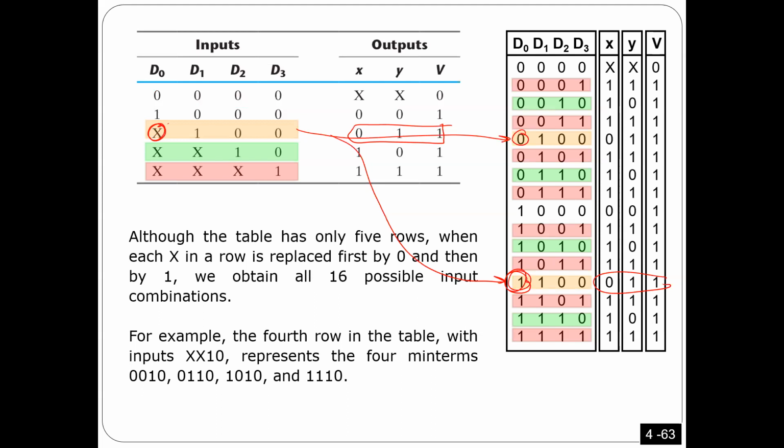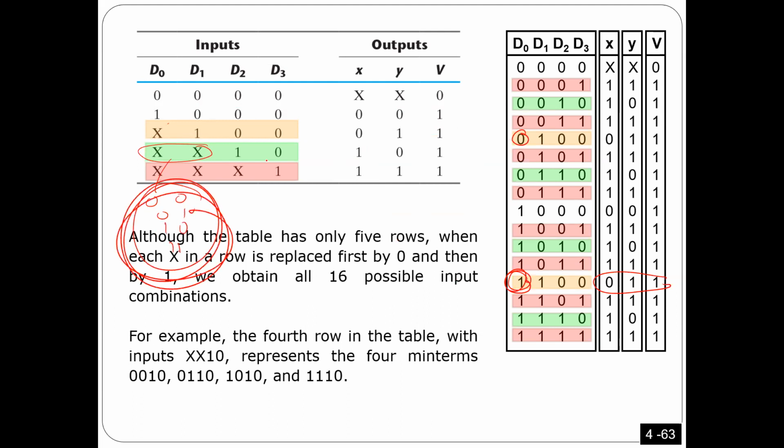It's like a minterm expansion. This is like a compact form. Okay. What about this one here? This is actually 4 cases. It means if the input here is 0, 0, or 1, 0, or 1, 0, in any of these cases, given these fixed cases, I have to see this output.